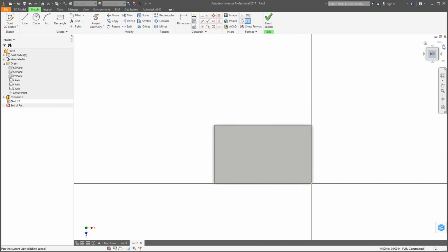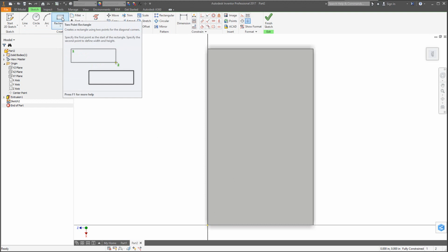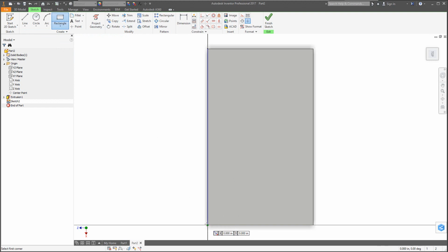Okay. And again, you could go up here, hit this little arrow to the right. Now, if your orientation is different, don't be too worried. Remember, it's all going to come out just right as long as you keep your mind oriented in 3D here. So with that being said, now I'm going to go over to the rectangle tool and click on it. We're going to use 2-point rectangle again. Now move your pointer down to the lower left corner. You'll see the green dot again. Click, and I'll drag this over. Now make sure that edge highlights, and it's going to snap to that edge.